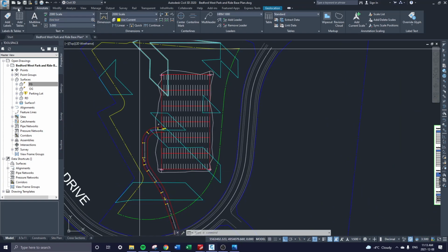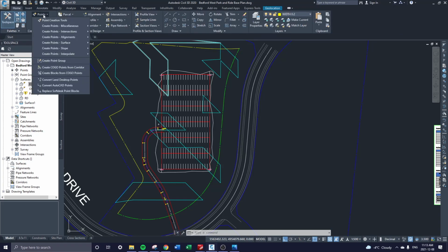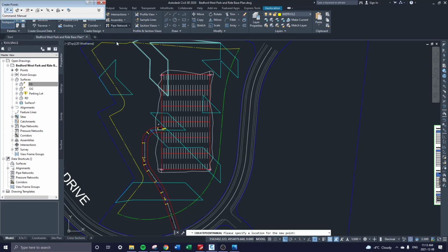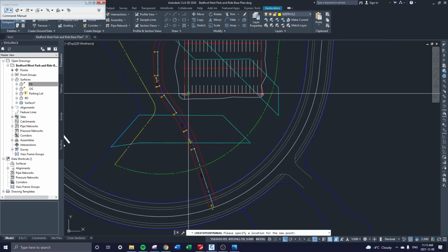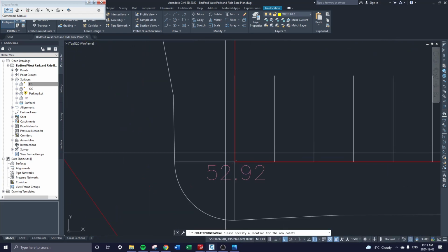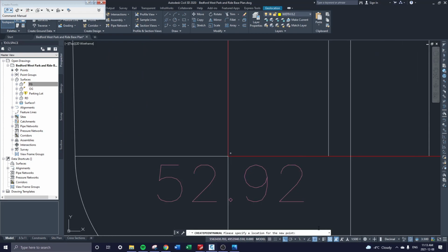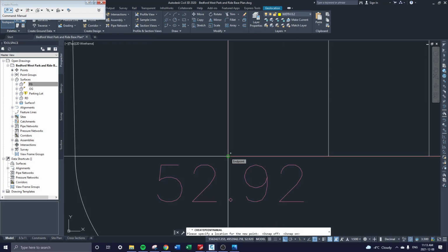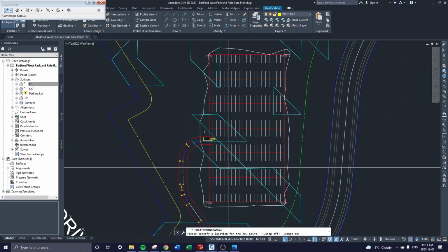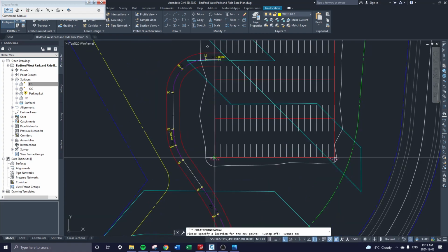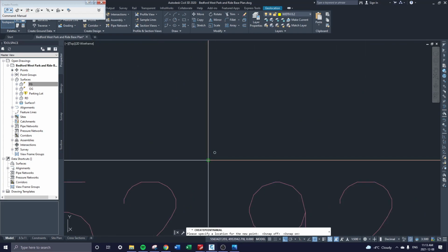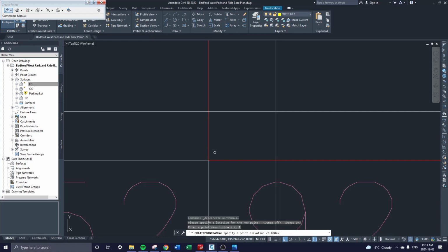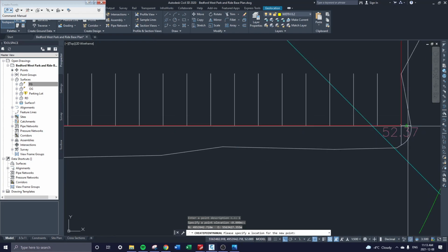So it is essentially make points, right? Manual. Honestly, manual is probably the easiest way. So it's pretty much just click and place around the parking lot. This one might be useful to put your snaps on. Remember, F3 is your snaps on, snaps off for quick access. Okay, so we'll call the parking lot points, like maybe we'll just call them 1, 2, 3, 4. Okay, bam. What's the description? Well, we'll call that one elevation irrelevant, and just kind of work your way around.